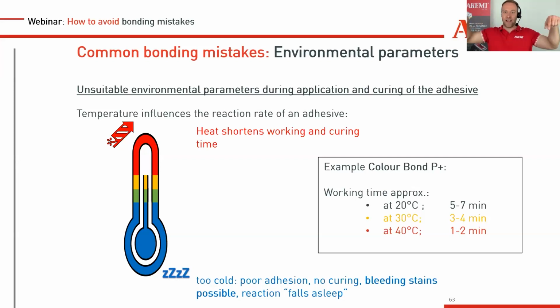When you have a nice island countertop and you have to do a few meters, let's say 5, 6, 7 meters around, and you put the glue everywhere, and suddenly after 1-2 minutes it starts to get chilly, it starts to cure. Then when you start to press the stones together, the polymers have already started to react, so they will not have a proper adhesion, a grab and tack to the stone. So have that in mind.